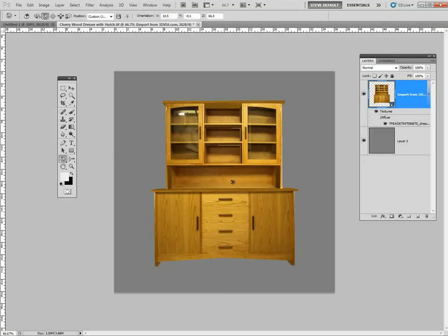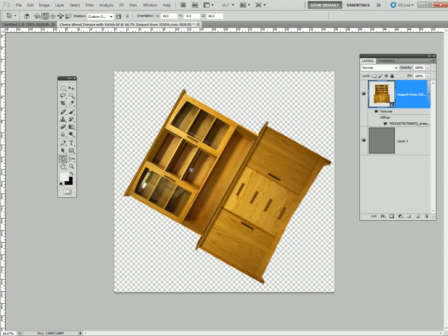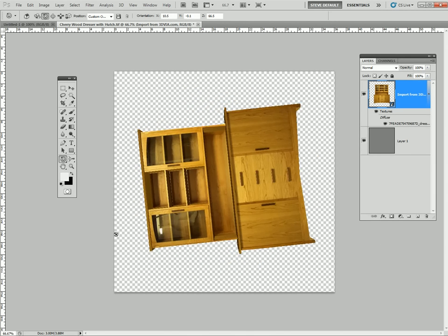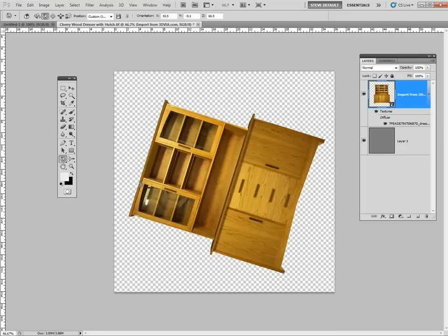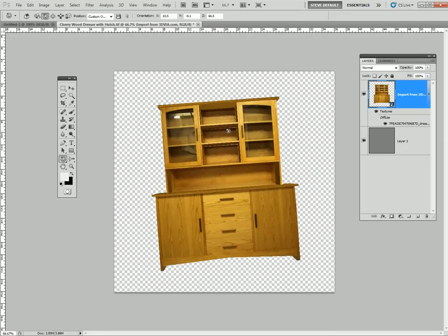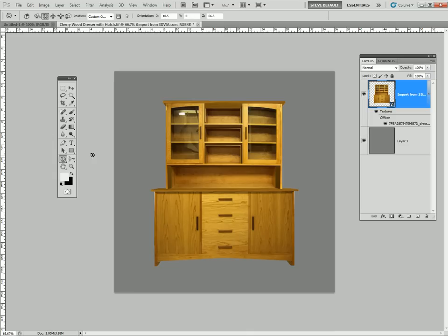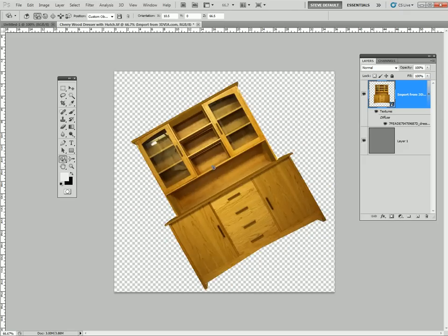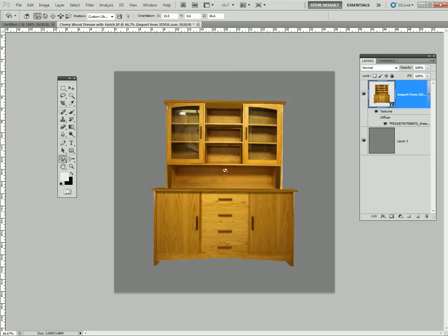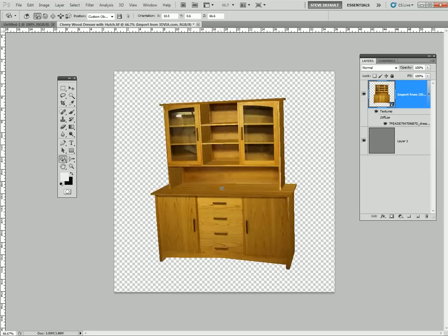If I click on the roll tool and click and hold, it's going to rotate around the z-axis, which is the axis going in and out of your scene here. It's your depth. Now, I want to mention something real quick about shortcuts. If I hold the Alt or the Option key, if you're using a Macintosh, while I'm in the rotational tool, I will automatically get the roll tool. If I release the Alt or Option key, that would automatically take me back to the rotation.